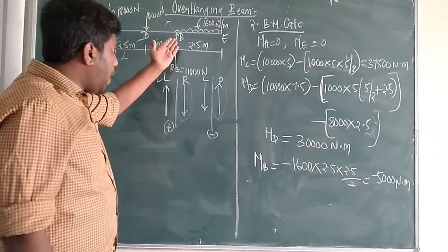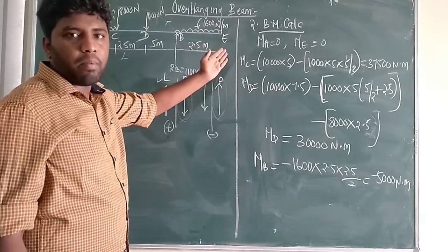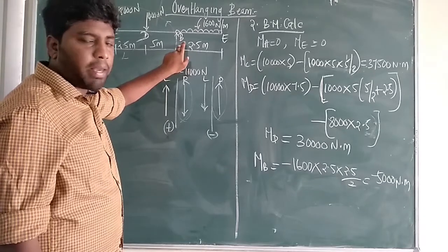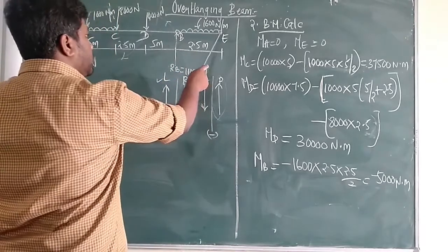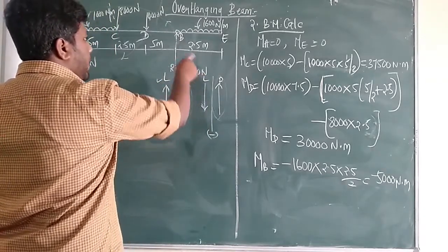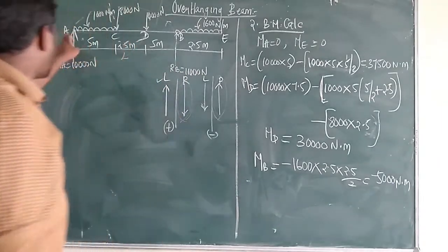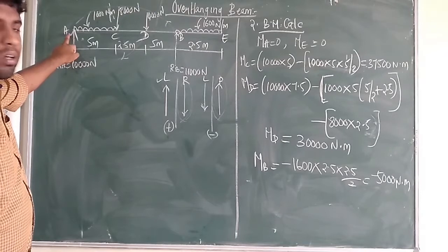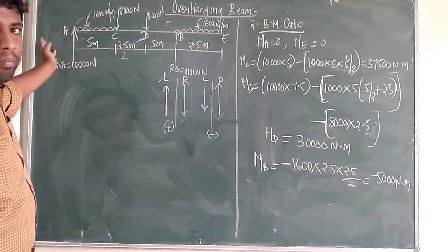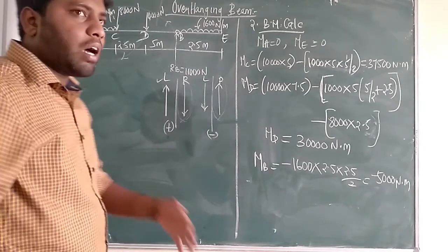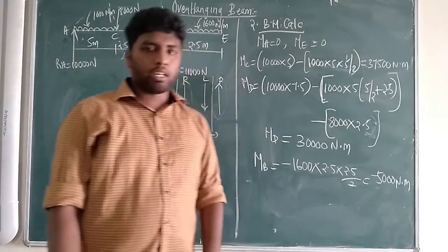But at point B there is an extension of the beam till point E. So this will not be 0, we have to calculate moment at B because here this beam will make a moment at point B. So at this support there is no extension. Okay, so this moment at A will be 0, and there is another rule. Rule number 8.